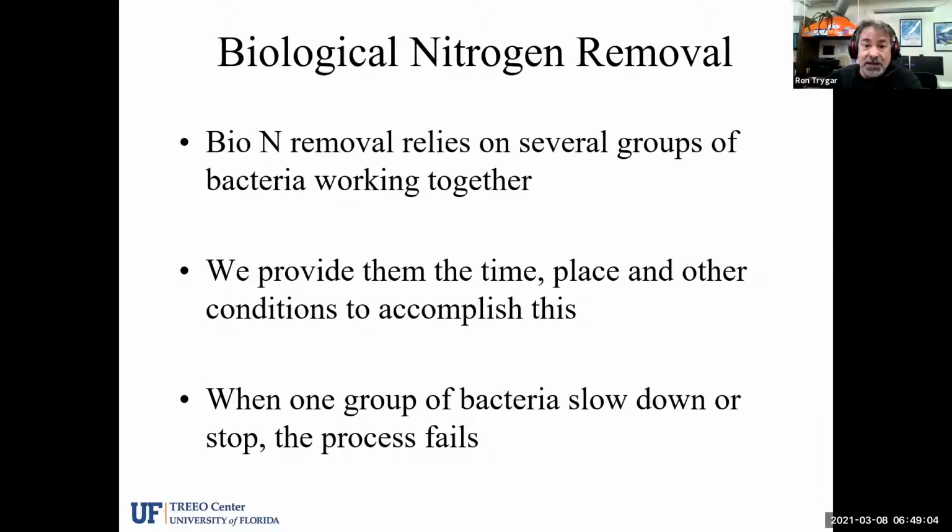So you're going to hear me say alkalinity a lot in this session, and I really hope that it gets ingrained in your mind how important alkalinity in the form of bicarbonate is to this process. And many operators tend to forget that that is such a necessary component, and we don't measure the alkalinity coming into the treatment plant, or we don't measure it through the process, and it becomes one of these lab tests that we tend to forget how important it is.